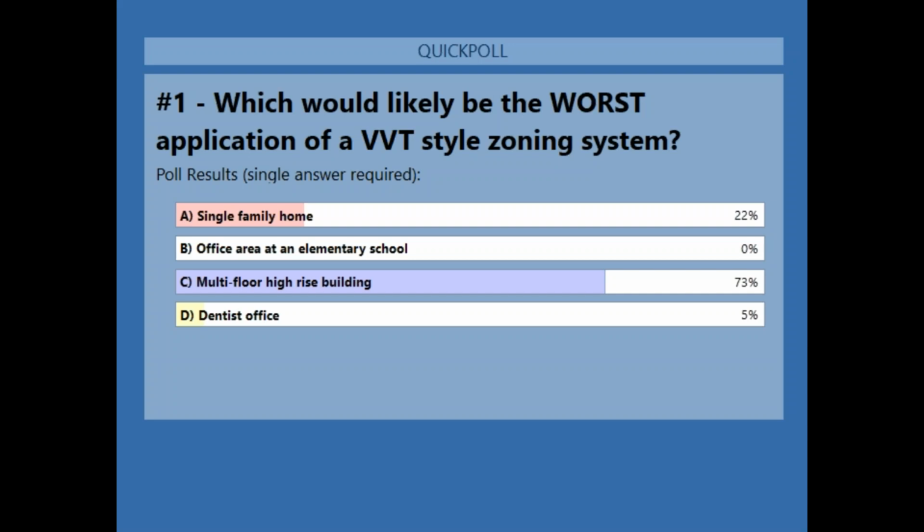We got a question here that came in from Chun asking how we could determine between a rooftop and an air handler. On the surface, that's an easy question, Chun, but it's actually a really good question because those things get confused a lot. For starters, a rooftop unit is always going to be installed outside. It'll never be physically inside the building. Now, it might be on the rooftop, and it usually is in our marketplace, but sometimes it's on the ground next to the building. And when it is, we still call it a rooftop.